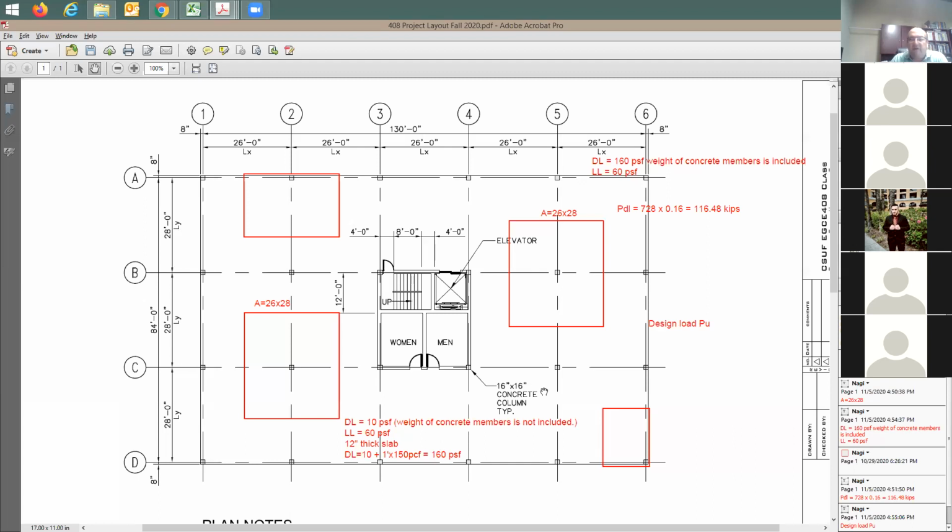So again, you're going to have a column design: short column, or let's say small eccentricity column, balanced point, tensile strength of the column, load combinations, M sub U and P sub U given some combination, and I ask you about the capacity. Is this column okay or not?